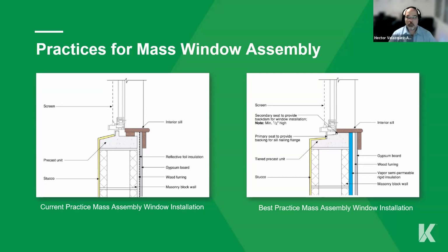So it's always going to depend on the product that you have and the maintenance you do on your building. If you're cleaning your building constantly, every product will last a little bit better and longer. But typically in Florida, you get waterproofing that is going to be 5 to 10 years. Maybe you're going to do waterproofing on the horizontal surfaces. On your vertical ones, usually it's 5. Now you're going to get some warranties that go a little bit further than that. But typically, due to the sun and exposure that we have in Florida, 5 to 7 years is the typical average.